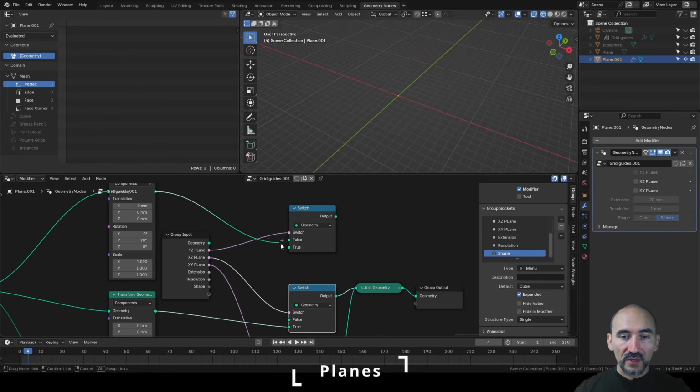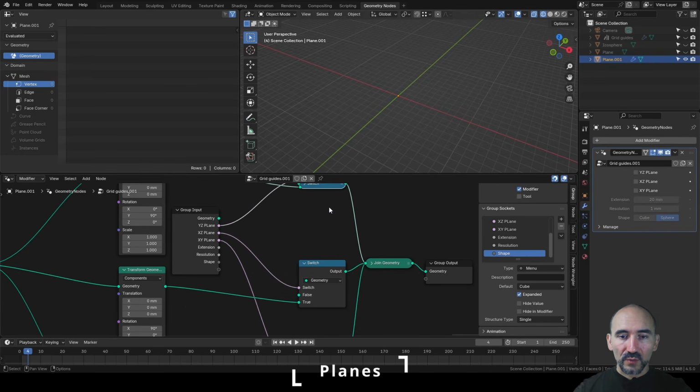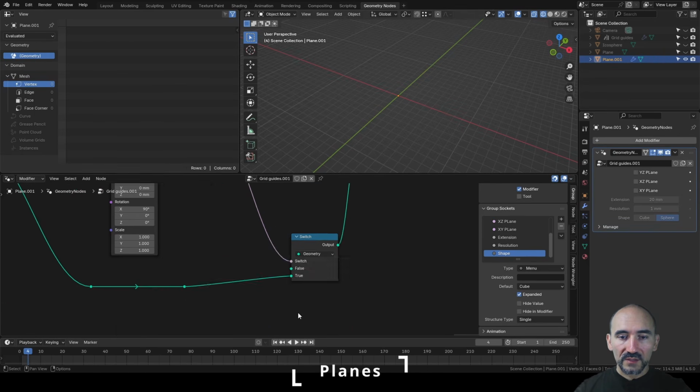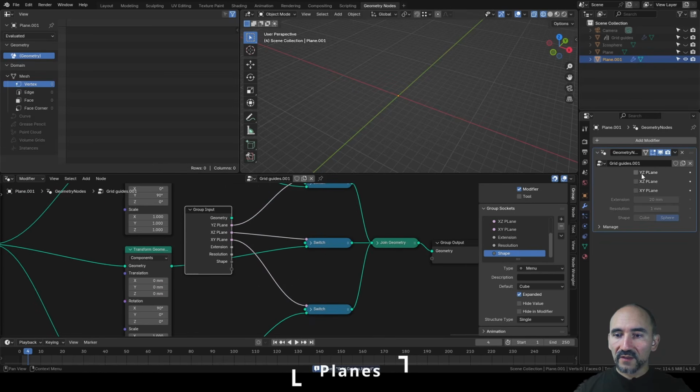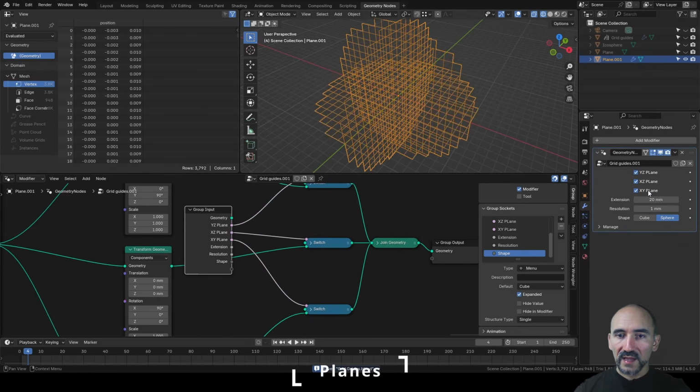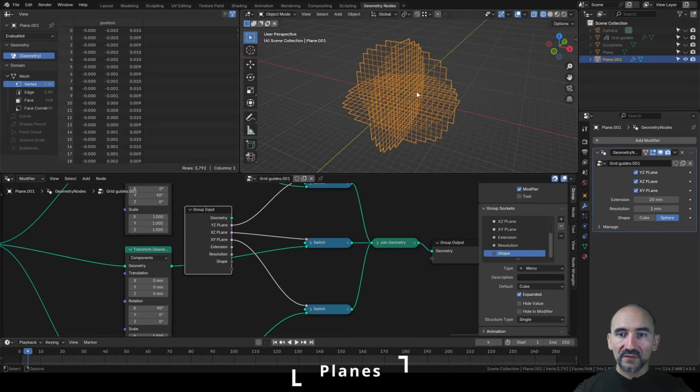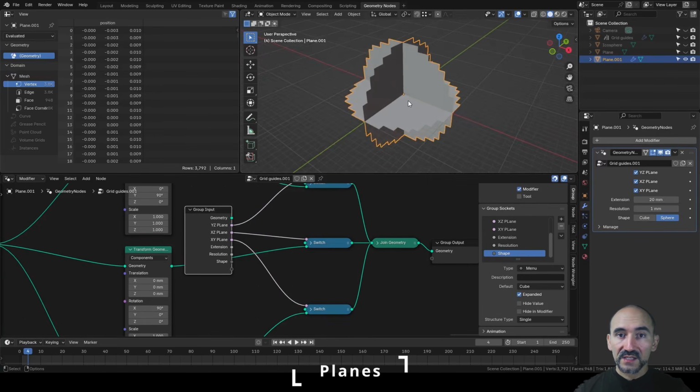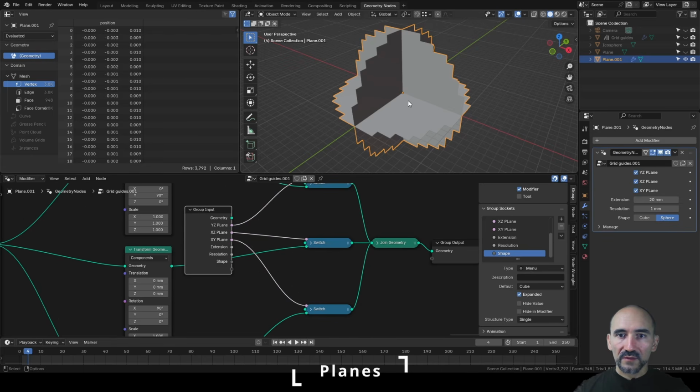And if we want to have this result, so the Y and Z, so this plane here, that is the original rotated on the Y axis by 90 degrees, we can link these in the geometry. Press H to collapse, H to collapse, H to collapse another time. And now if I enable each of these planes, you can see the result inside our viewport. And remember, in this moment, we still have faces. So if I press Shift Z another time, we still have faces and we don't want them at the end of this tutorial.